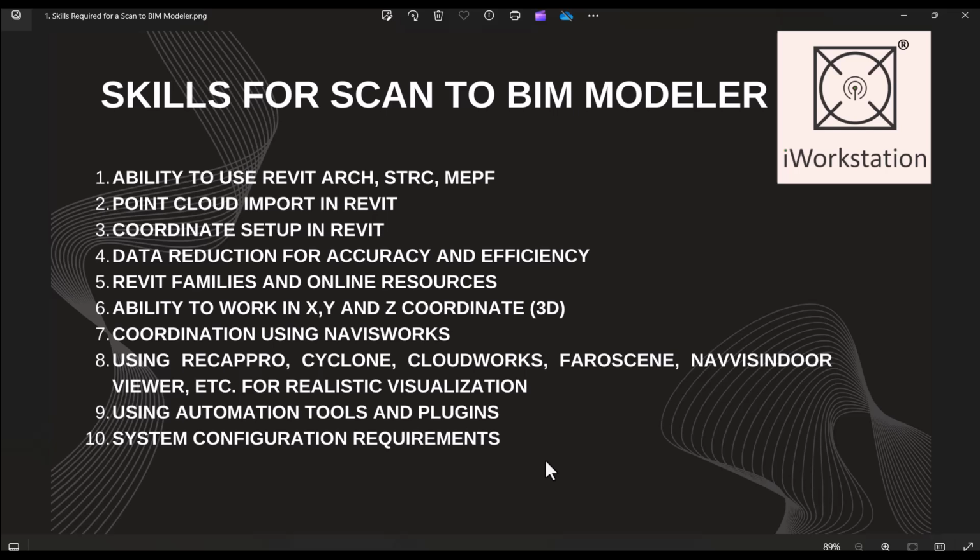Then coordinate setup in Revit. So imagine you have a building, and that building is at a particular location. I'm saying like in New Delhi. In New Delhi you have to develop a particular coordinate system where you can establish these coordinates in Revit. So when you receive the file, you will also receive the coordinates for that particular location. So you need to do a coordinate setup.